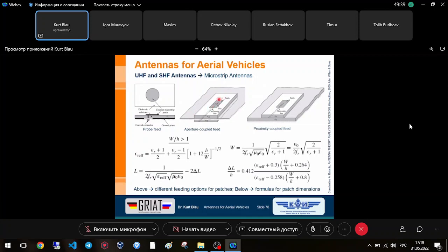This is the radiating patch, and the rectangular slot is etched in the ground plane, and this gray rectangle is our radiating patch, and this broken line is the feeding microstrip line for this patch. It's only a second possibility to transport the electromagnetic energy through this slot to the patch.